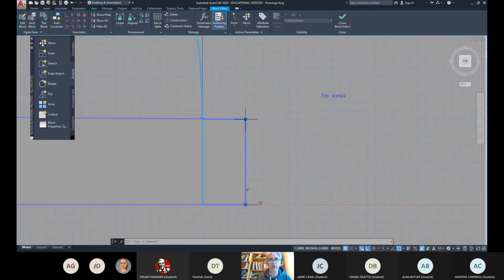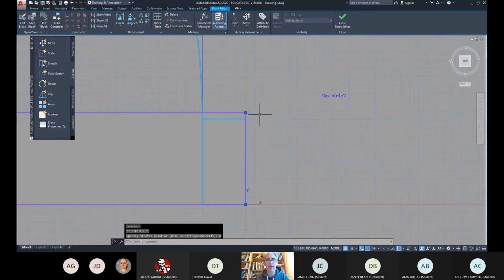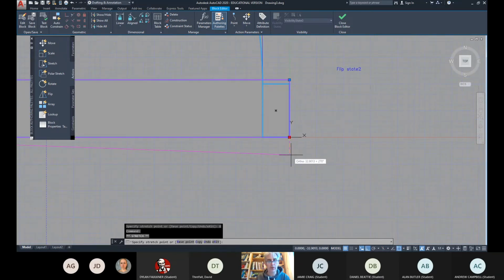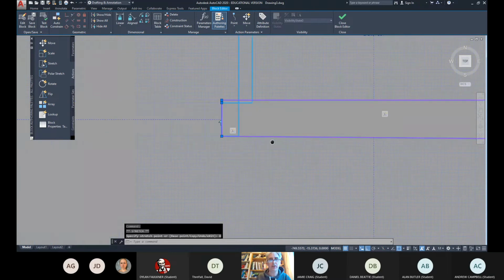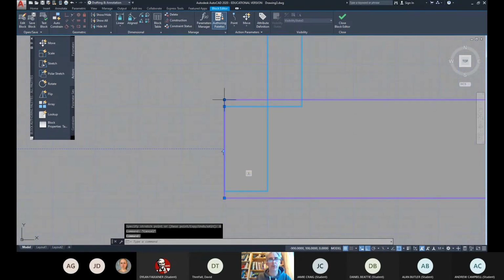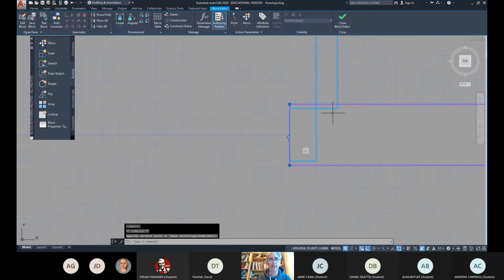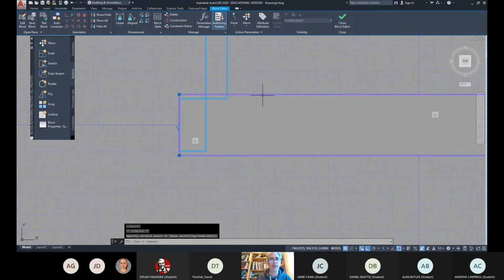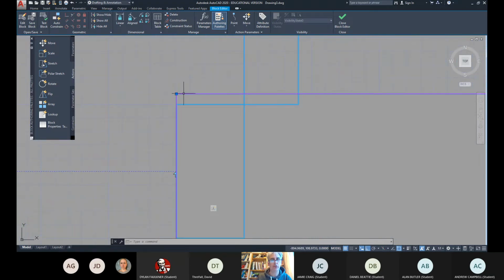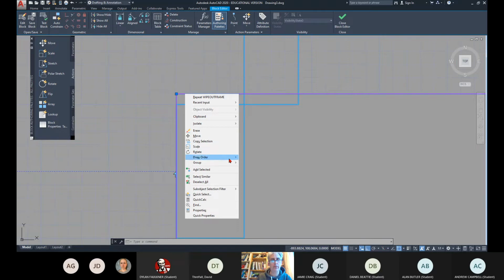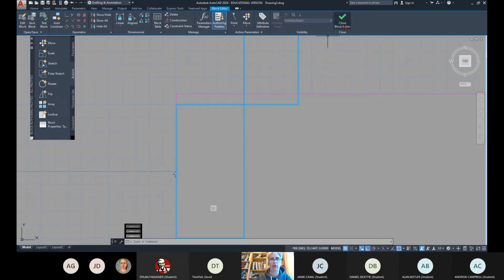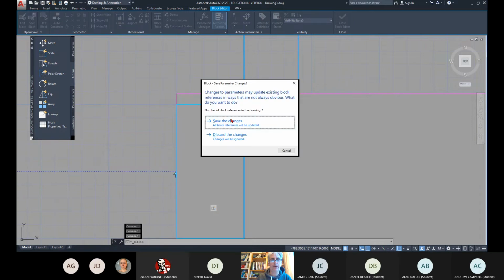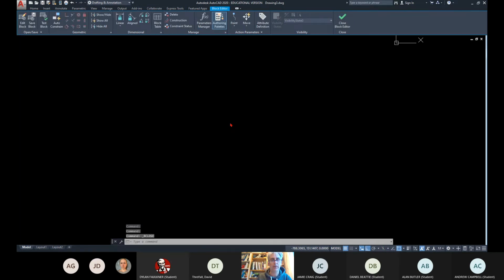Go over to the other corner, stretch it up that way by 8, and do the same to all 4 corners, stretching each one out the way by about 8 millimeters. If it doesn't work, then we'll just have to go for 10 millimeters. Okay, so you see what I've done there, right? It's still set to back. It's still at the back of that door, right? In terms of the draw order. Yeah. And then close block editor. And then save the changes again.